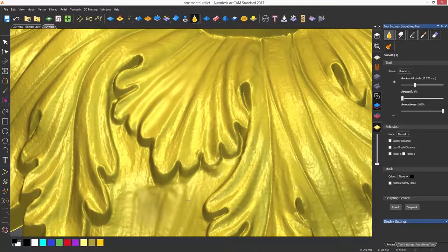The smoothness section affects the drop-off of the tool. A smoothness of 1% will give a sharp 90-degree edge, whereas a smoothness of 100% will give a gradual drop to give a nicer blend when sculpting. I'll explain the behaviour section in a moment, as I need to switch to the deposit tool so you can see what is happening better.